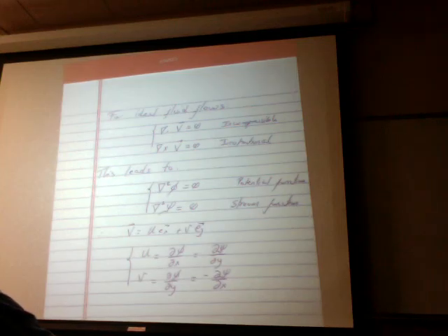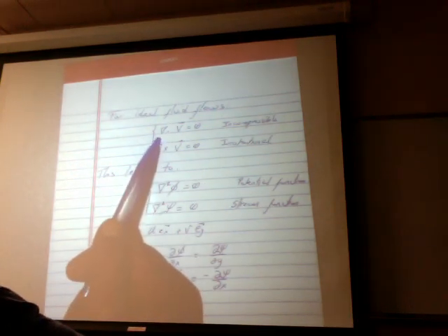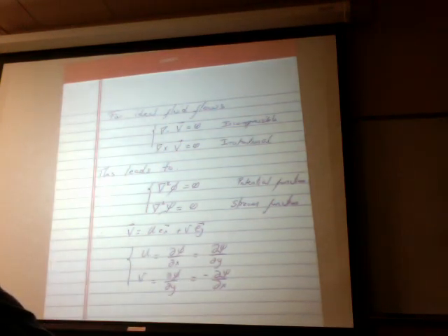And this all came from an implementation of the Gauss divergence theorem that led us to find out that when a flow can be considered to be incompressible, the governing equation is divergence of V is equal to 0.